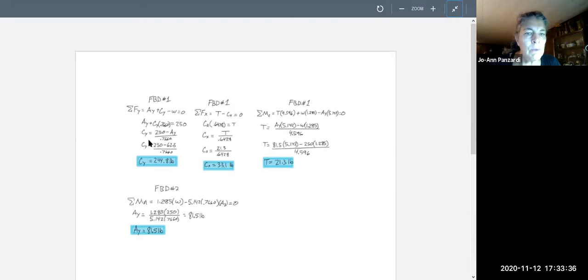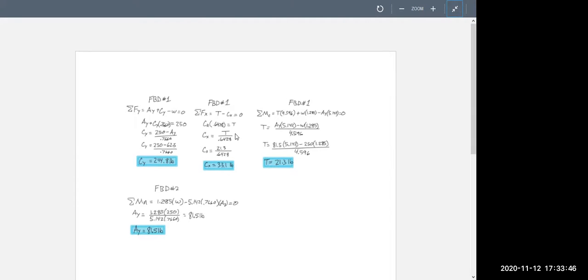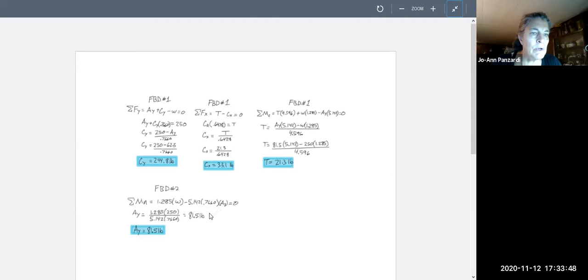So if you want to set it up like this, then you have to say how you got the AY, like maybe draw an arrow and say, oh, I plugged it in here, or T, I plugged it in here. But the better thing to do would be to solve the moment equation and solve for the unknown, and then do the sum of the forces in the X and the Y so you could start plugging numbers in. Does everybody see that? Give me a nod or something.